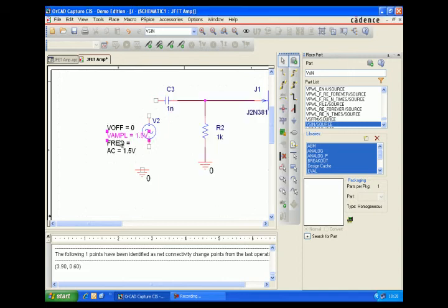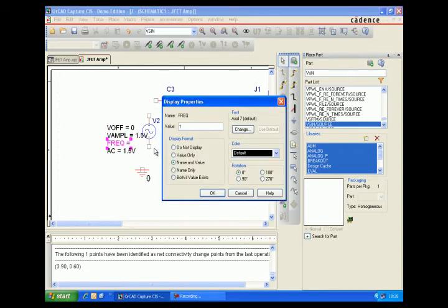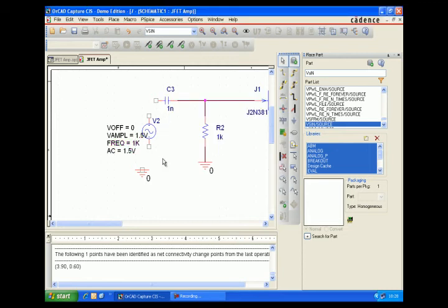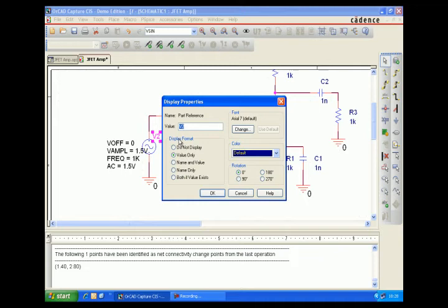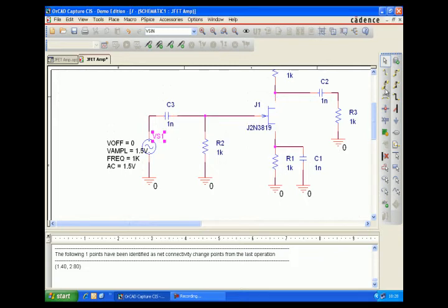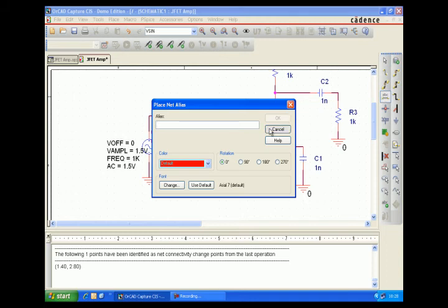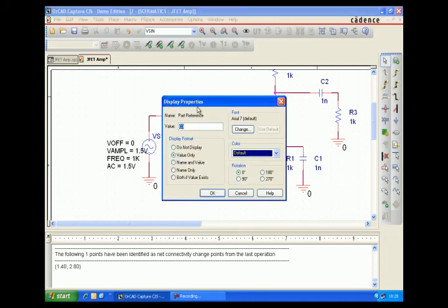We have V of 0 connected to the ground and one side connected to the coupling input capacitance. CC1 is the input coupling capacitor. We need 0.1 microfarad. That's a net alias for Vin.